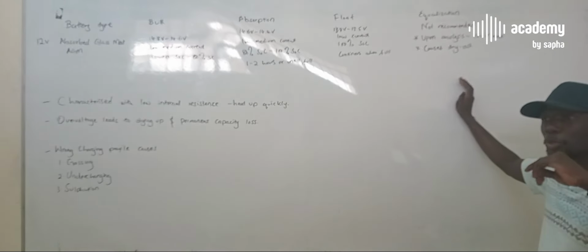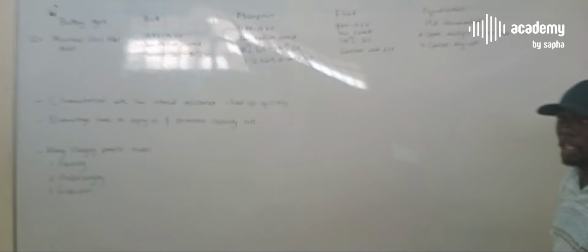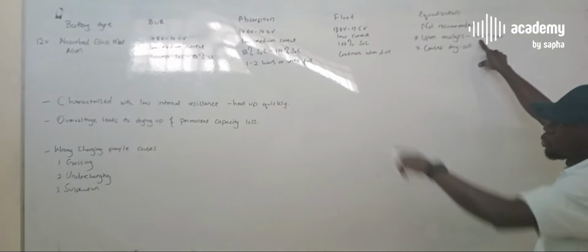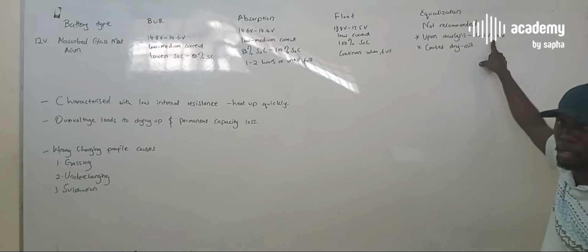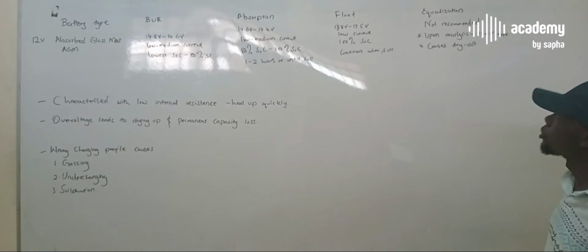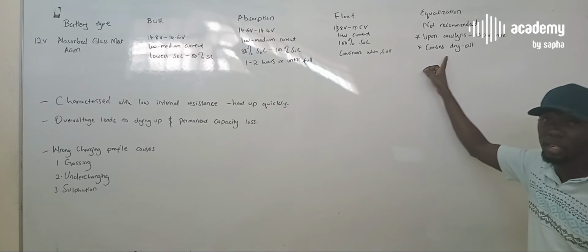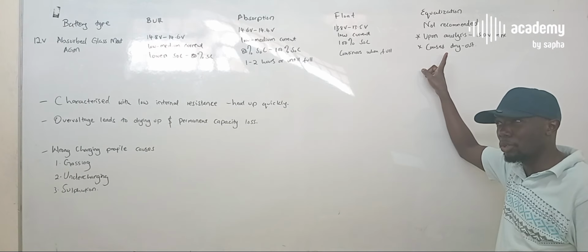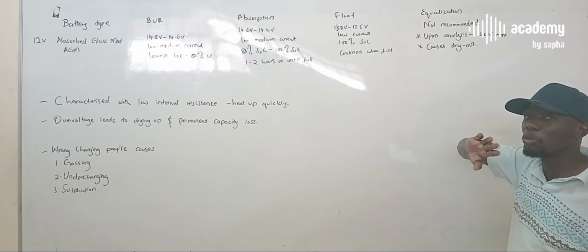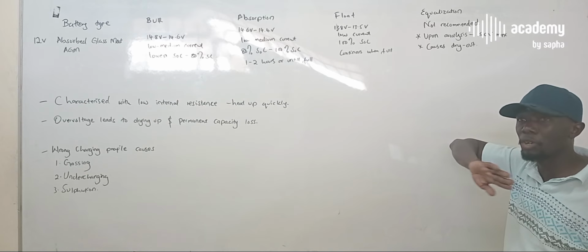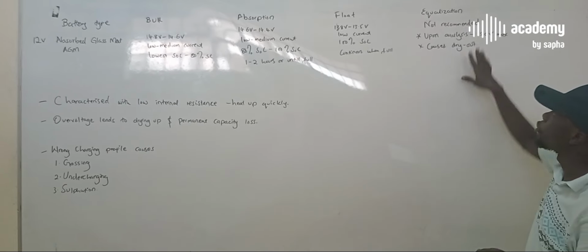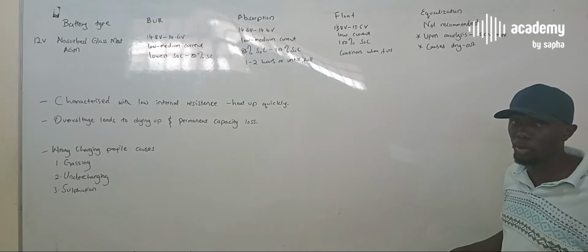But if you have a technician who has analyzed the system and understands it, the maximum voltage you can push into an AGM battery for equalization is normally 15 volts maximum. And according to the little research that I've done, don't do it for over 1 hour, maximum 1 hour, and it should be not as frequent as for flooded lead acid batteries. You can avoid it altogether for this system, there will be no issues.